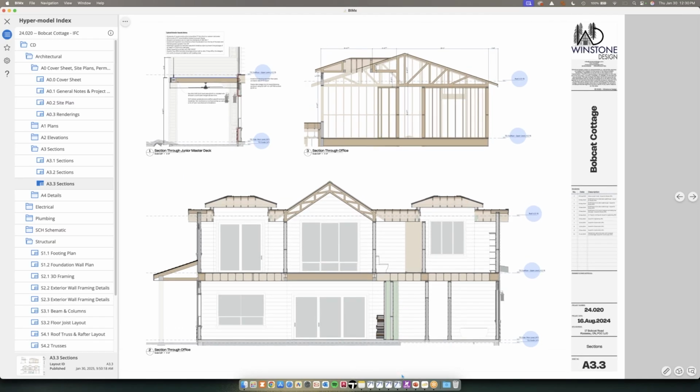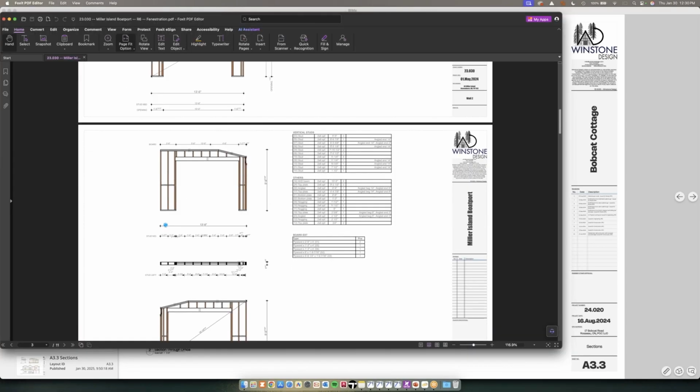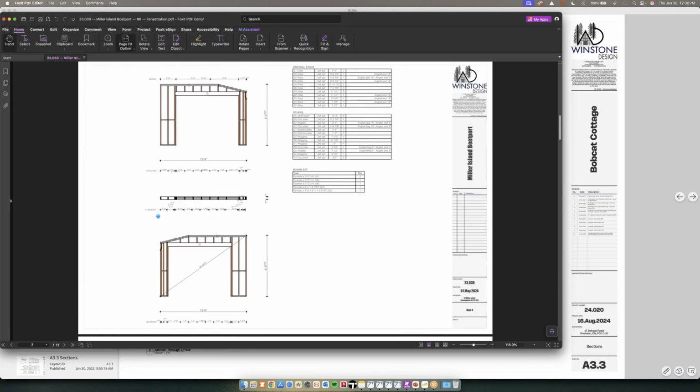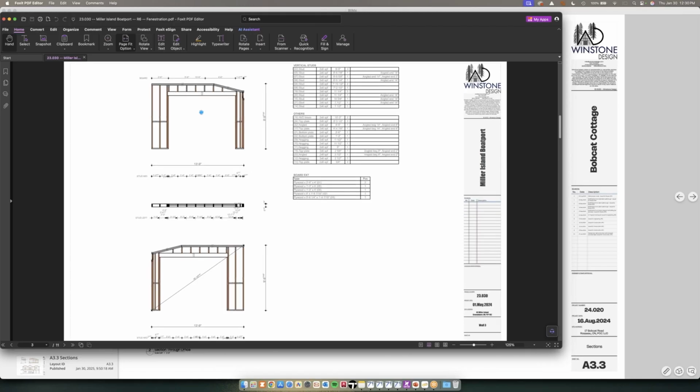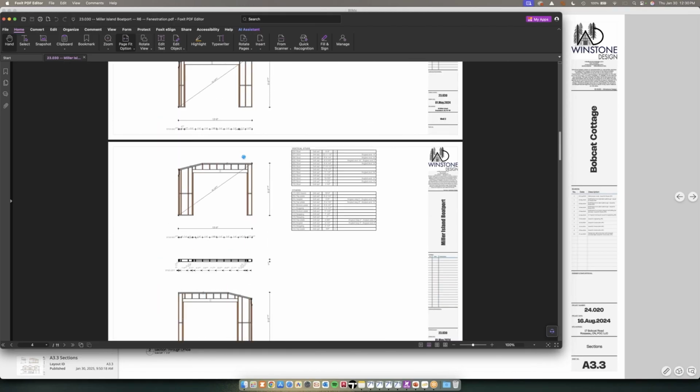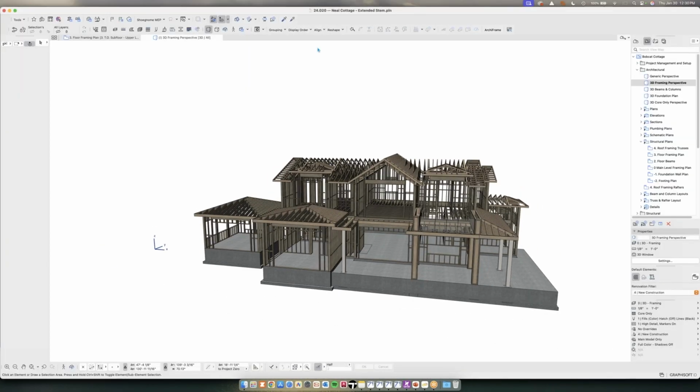And then working closely with ArchiFrame, the output for wall framing, for example, as Tom sort of alluded to, the documentation is automatically generated from the ArchiFrame wall element tool. So it gives you cut lists, it gives you beam locations, it tags everything with dimensions, it gives you squared off dimensions here, it gives you cut lists even for paneling. So in terms of ease, in that 12 to 13 hours that it took me to frame out that building, it now automatically generates, if I go back to here, for example, the wall framing layers.